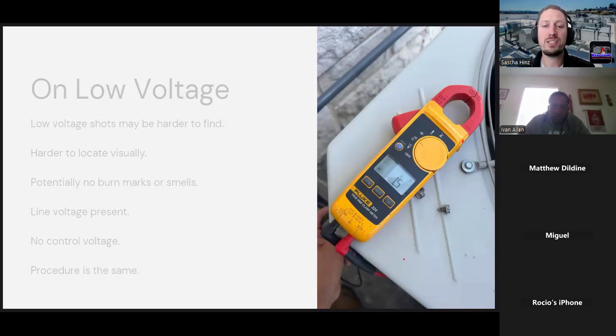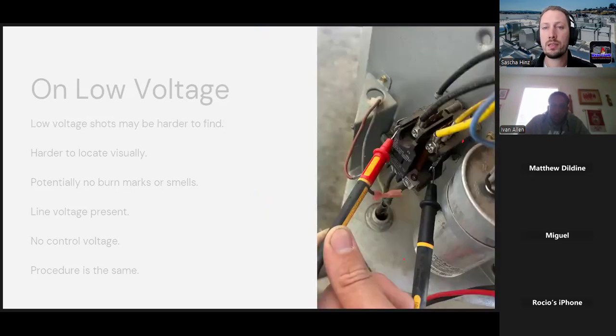One thing that I could advise you to do is test resistance on new components that you're installing. I used to do that quite frequently. I don't do that as much anymore, but specifically on contactors like this, I like to know what the resistance is on the coil from the manufacturer. What I saw mostly was 7 to 15 ohms resistance as good. If it got below 7, I would get suspicious. But recently, I've encountered contactors that read 5.8 ohms on the coil coming from the manufacturer. I installed them and they're still working.